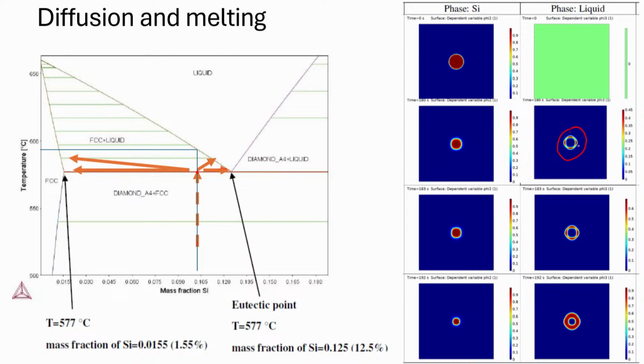So this is a test run, so we did a very coarse mesh. This should be circular, really. But you see how things are melting around silicon. Inside is silicon, outside is aluminum. And I think here this outside is aluminum plus maybe 10% silicon. So we need just a little to add to get to the eutectic. That's the lowest temperature where things begin to melt.